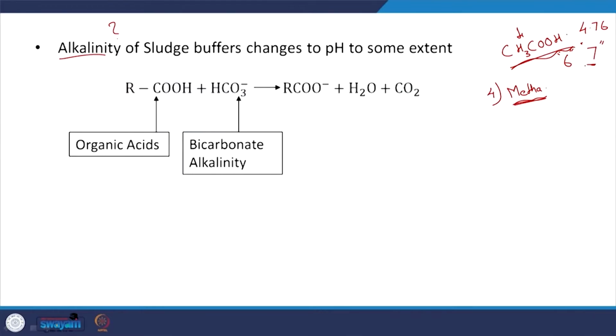And here is where alkalinity comes in, as in acidity, the ability to neutralize an acid. So, in general alkalinity, I guess we did talk about this earlier, but let me just write down the equation. I am writing down the relevant bases that will come into play if we are titrating usual waters or natural waters from the relevant pH to a pH of around 4.5, that is the standard method definition. And because these are the usual bases that you will come across, that is why we have these.